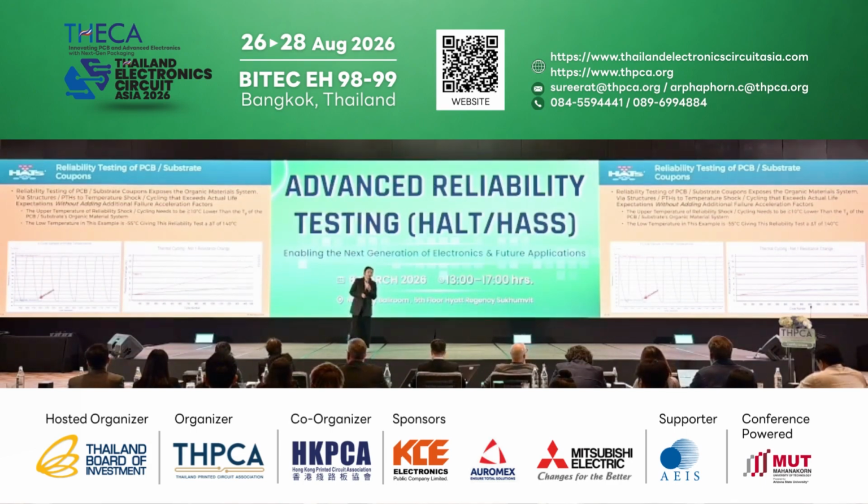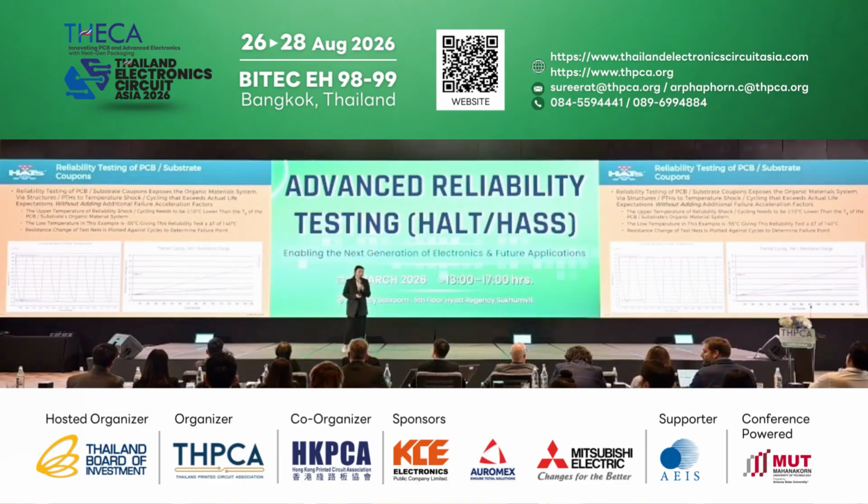The upper temperature of reliability shock or cycling needs to be typically 10 degrees C or lower than the TG of the PCB. That's when we don't want any additional failure factors. At the high temperature, we just use anything 10 degrees or lower than the material TG.